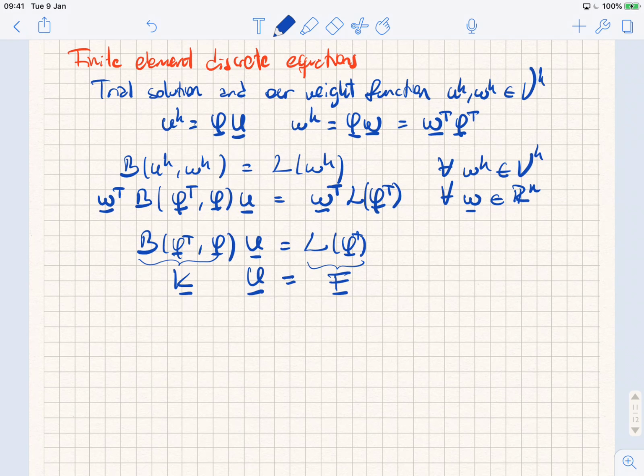You could see it written like this, or perhaps like this, which would make more sense. But in finite element analysis, everywhere you look, you see it just written like this, but it is understood that here we're multiplying a row vector that contains your shape functions, and U is a column vector, right? I also think it's slightly weird, but that's the way it is in the literature.